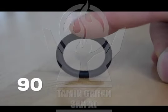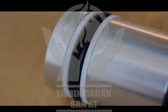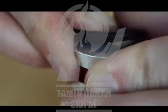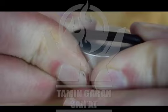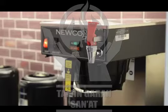90 durometer is extremely hard and consequently is more resistant to extrusion. For higher pressures exceeding maybe 6,000 psi, you'll definitely want to consider using 90 durometer. However, the better high pressure performance comes at a price. 90 durometer O-rings can be really difficult to install, particularly in small sizes.